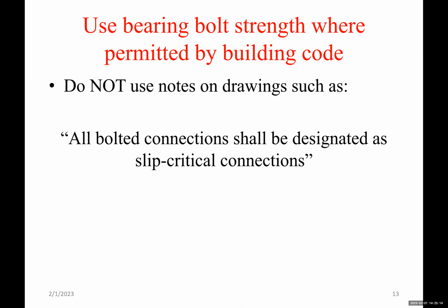So if you don't have to use slip critical, then there are many considerations that you have to take. So do not use notes on the drawing such as all bolted connections shall be designated as slip critical connections. There's no need. That's a lot of preparation for all bolted connections.